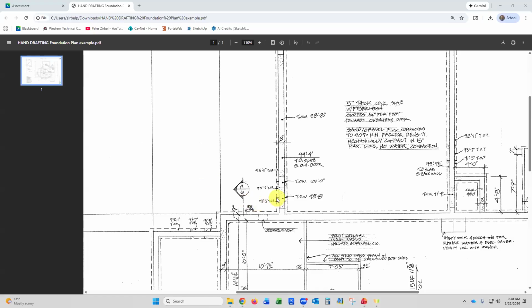Okay, so what I'm doing by this little horizontal line is, if I was looking down at that footing step, that's where I would see the step, right? Because the footing's sticking out on each side of the wall, I would see that step. So there's a horizontal line there and there that's showing that footing is stepping up. And then I'm telling them the top of footing there.